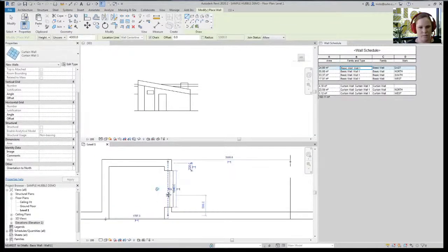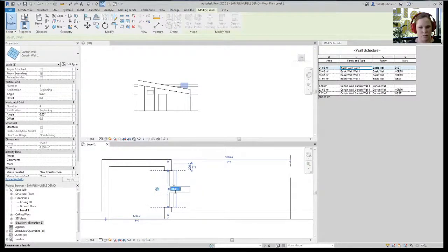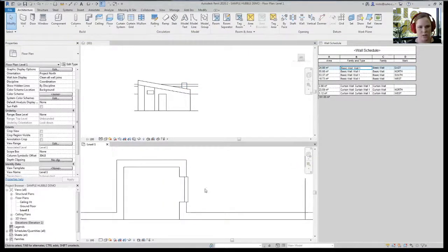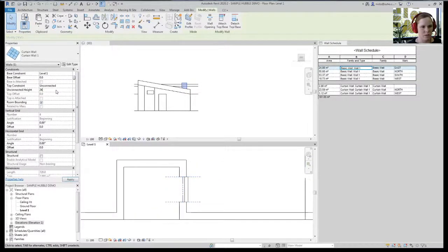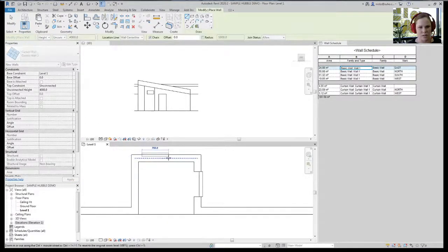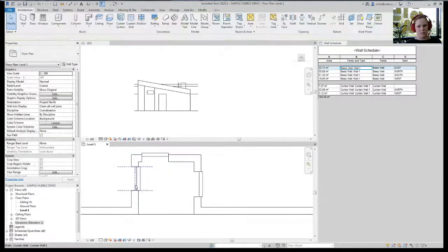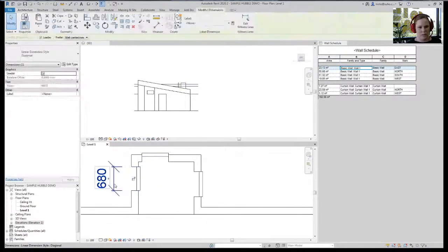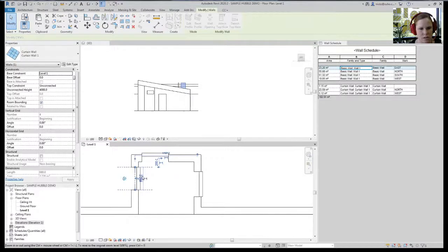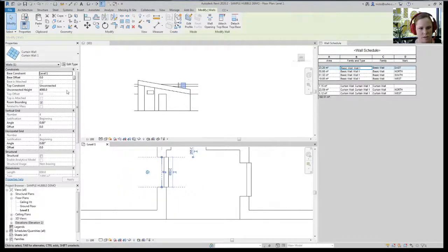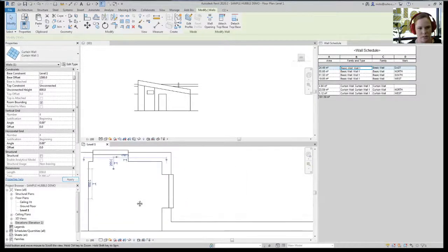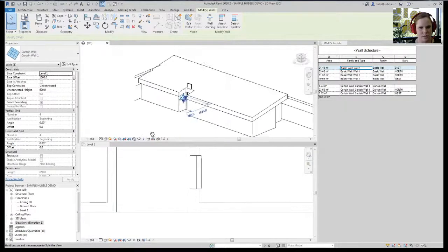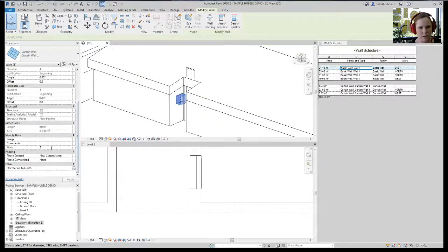So now back in Revit. Going to give the width of the door, good, 720, and we're going to just assume the height of it is 2400. Okay. 2100 I think is actually what we did, just so the head height's matched roughly on these. Okay. So we're going to select this. Don't actually need the dimension. So we're going to change these bathroom ones as well. Again, we will allocate which orientation they're facing. 600. Base offset we're going to estimate so that the head height is 2100. So you can see if I rotate around here, you can see that they're embedding. And then also that is east facing.